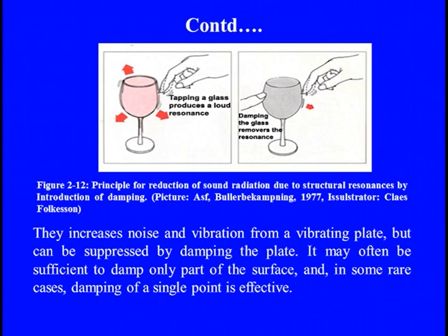This is another example. When we have a vibrating plate and we simply put any kind of damper there, it can straightaway absorb whatever the exciting energies are, and through this absorption the excitation level can be reduced. Just like you see on the screen, we have a cup. When you excite that by any small impact, a huge amount of vibration or sound can be generated. But even while we are exciting this, if we put another finger which acts as a damper, whatever forces come under the excitation by the finger can be absorbed by the other finger.